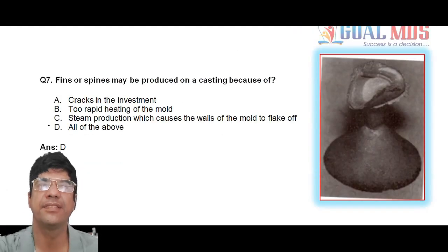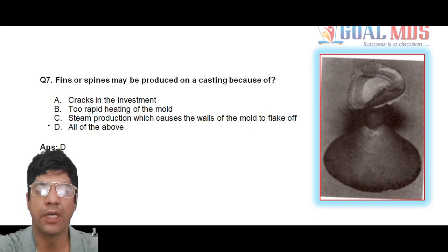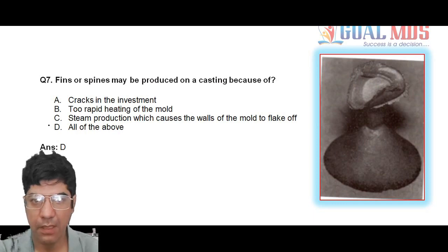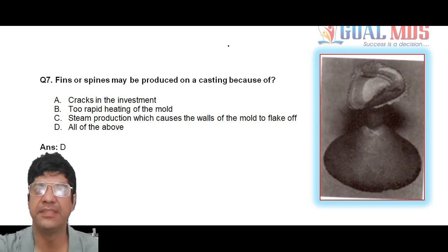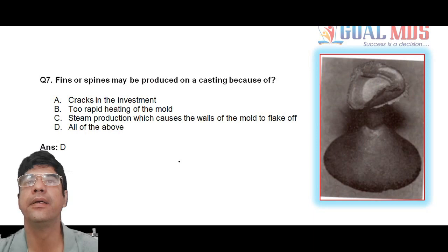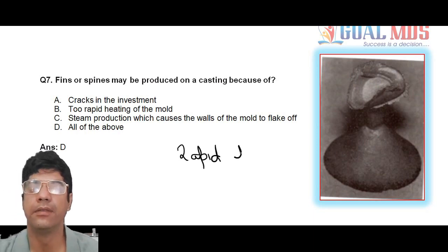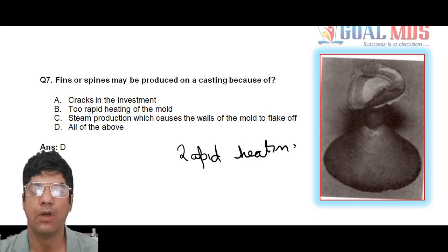The fins or cracks may be produced on casting because of rapid heating of the investment material. Fins and cracks represent the casting defect caused by rapid heating.